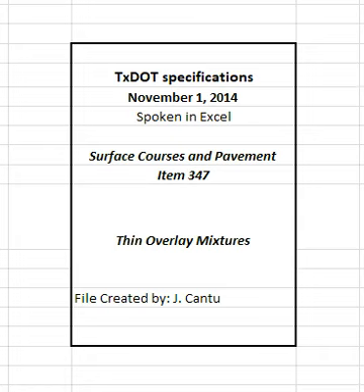If the department's or department-approved laboratory's sample from the trial batch fails the Hamburg wheel test or overlay test, the engineer will suspend production until further Hamburg wheel tests or overlay tests meet the specified values. The engineer may require up to the entire sublot of any mixture failing the Hamburg wheel test or overlay test to be removed and replaced at the contractor's expense.